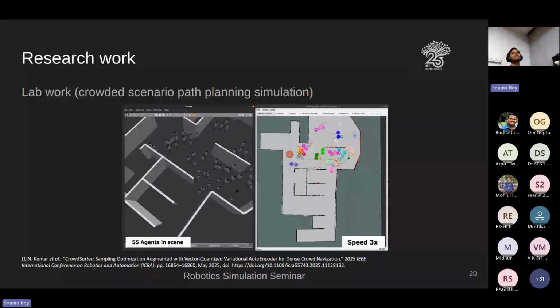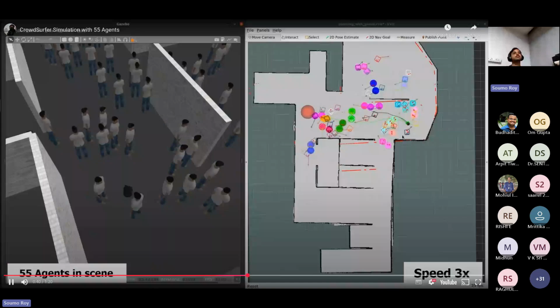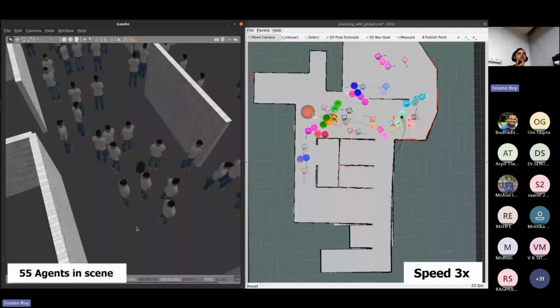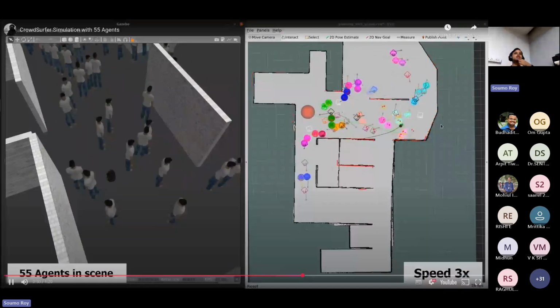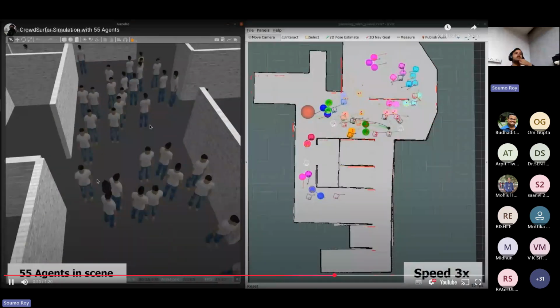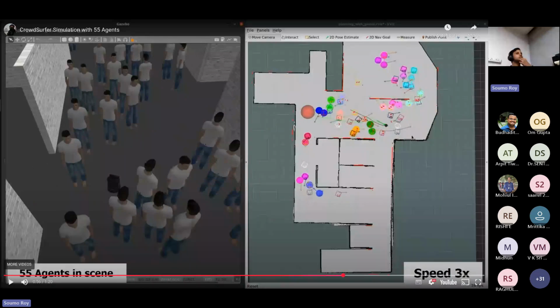Now you can see these red color points on a map. These correspond to the laser scan message, or you can see the point cloud that you are getting from the 2D LiDAR sensor on this robot. As you can see, it's trying to successfully navigate and avoid people in the environment. You see, this is also a Gazebo simulation platform and the same ROS platform too that we have used for visualizing sensor data and to also navigate a real world deployment.